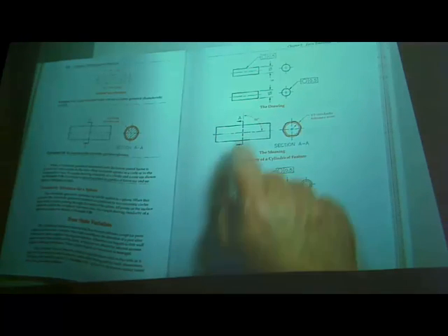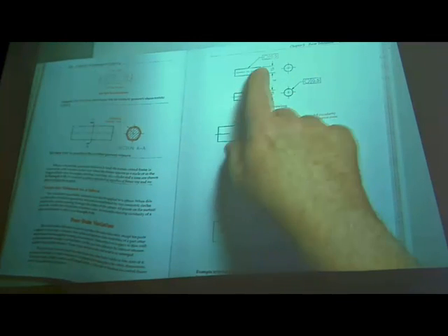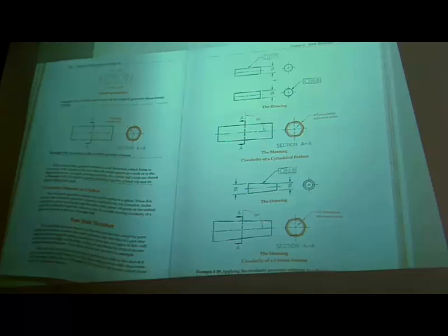And wherever the arrow is pointing is what we always used to tell our quality control or production personnel: where that arrow is pointing, that's where you measure. Measure one place. We might need you to check in two places, and we might specify that. But it's just check in one place. You don't check over the whole. For circularity, it's in one circular element. Okay? It's a pretty easy concept.